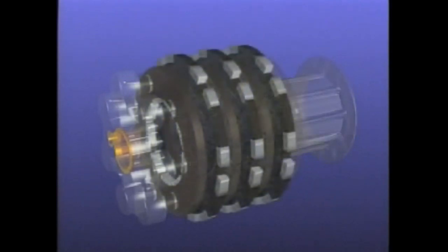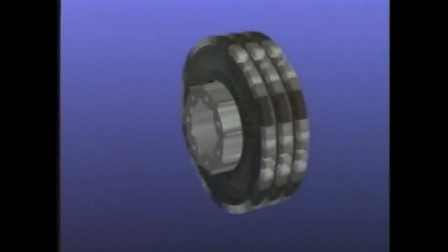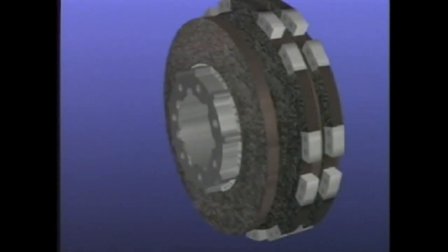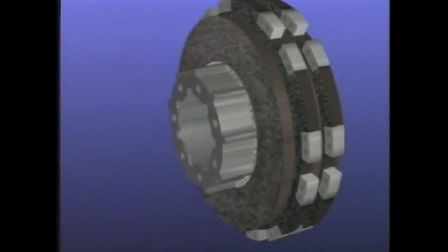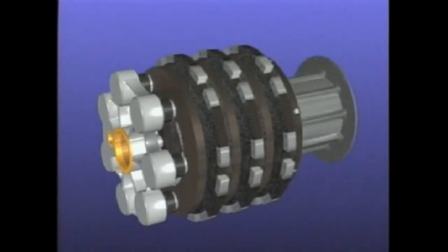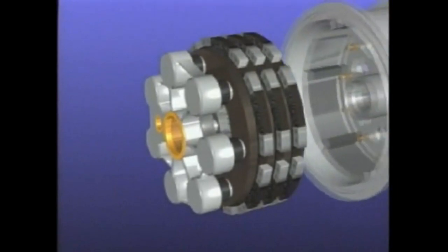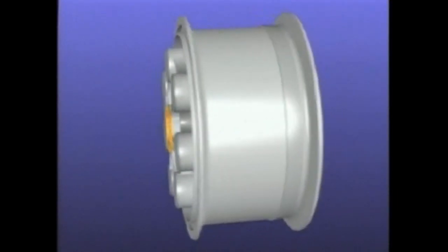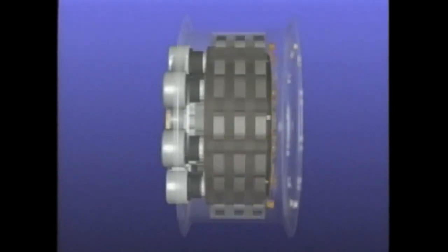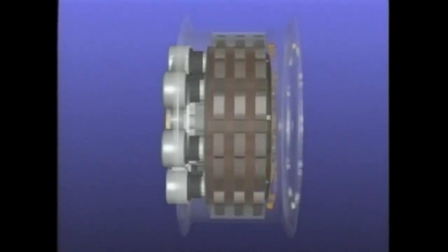The heat sink consists of alternating, rotating, and stationary discs. The rotating discs are driven by the wheel of the aircraft. The stationary discs are restrained from rotating by the keys of the torque tube. The piston housing is made up of forged aluminum and applies the squeeze force to the heat sink. When hydraulic pressure from the brake pedal actuates the pistons in the housing, the stationary and rotating discs are squeezed, creating brake heat and the drag forces that stop the aircraft.